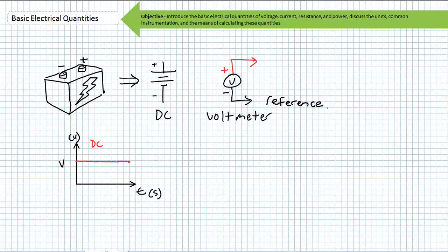If you measure the voltage of an ideal 12-volt DC voltage source with your reference on the negative terminal of the battery, the positive terminal is 12 volts higher than the negative terminal, and your voltmeter will read plus 12 volts. If you switch the terminal used as a reference, meaning you place the voltmeter reference on the positive terminal and measure the negative terminal with respect to the positive, the voltmeter now reads negative 12 volts, as you'd expect. The magnitude of difference is the same, in both cases 12 volts. However, you just changed your reference position. Like I said, it's all relative, just like the dating scene in Clackamas County.